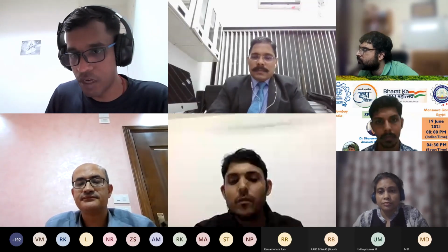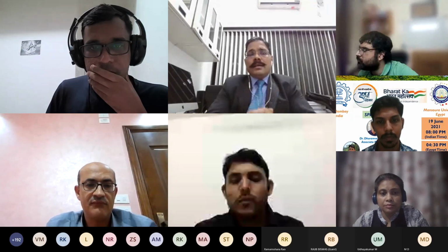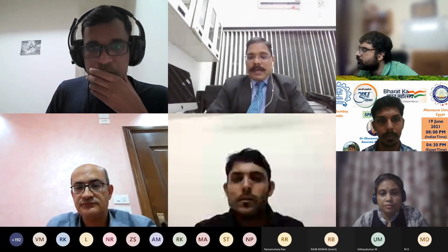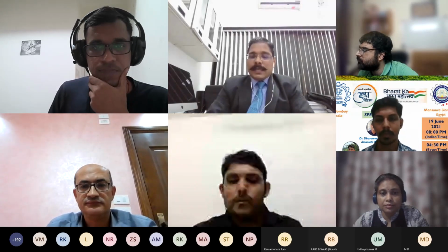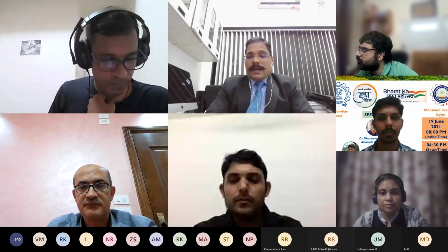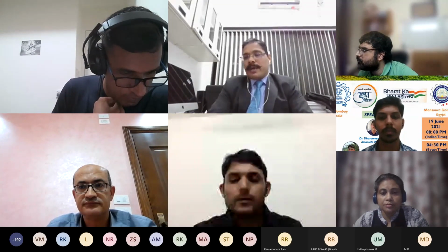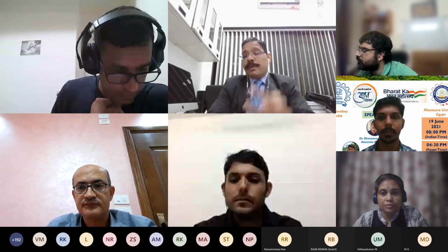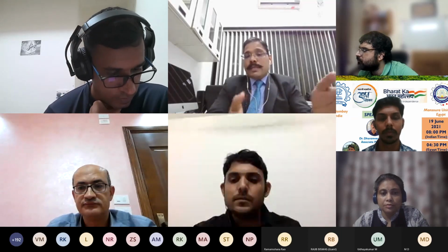Professor Singh would like to add further. Yes, I think you're right. There is another dedicated device that we have in our lab, called the GTR kit, that we use with the DSR. It is used exclusively for crumb rubber modified binder, because there are certain challenges in using the DSR for crumb rubber when you have larger particles that are not very uniformly distributed.